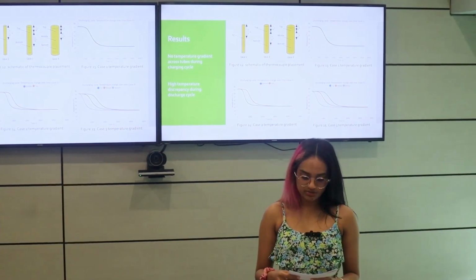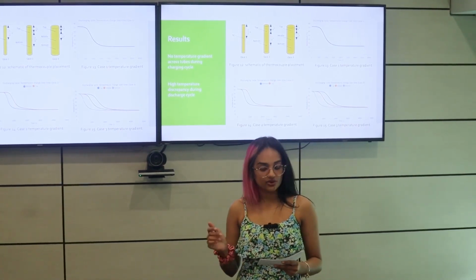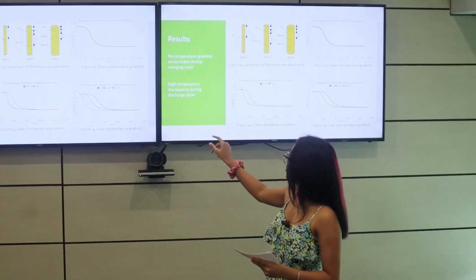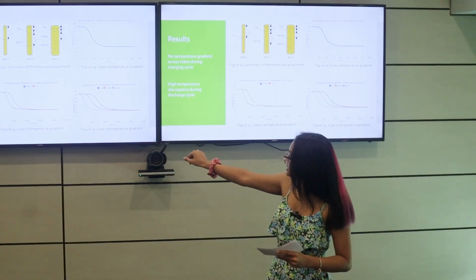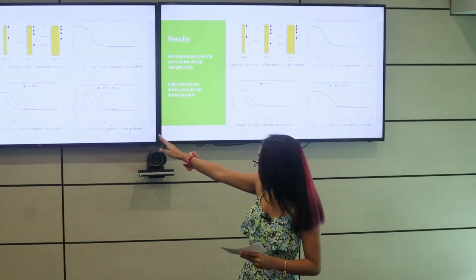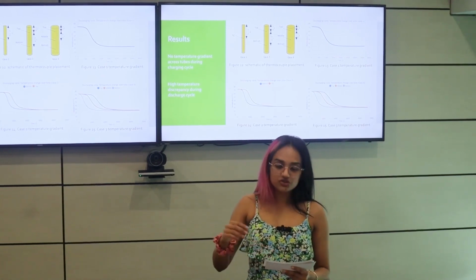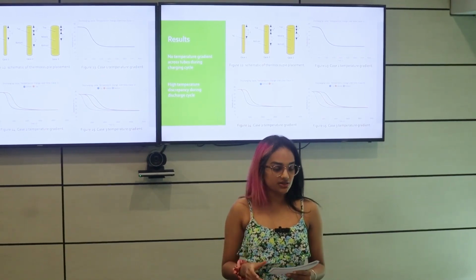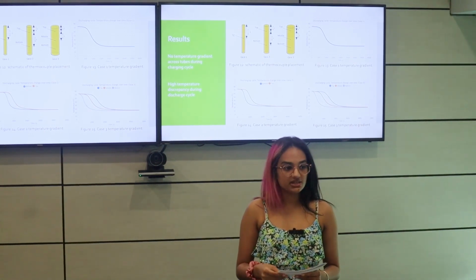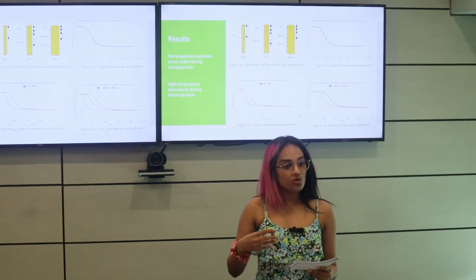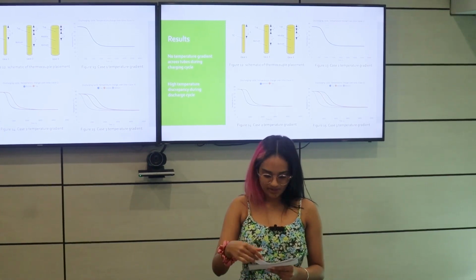One of the first observations to be made when I was analyzing the data is the significant temperature gradient which forms across the length of the copper tubes, as can be seen in cases 2 and 3. From these 2 cases, you can see that the bottom thermocouple and the top thermocouple were at extremely different temperatures at the same time. This gradient is as a result of the wax slowly solidifying, and as the wax solidifies, its density will increase, meaning that it will sink to the bottom of the tubes. The warmer wax will float to the top and be the last part to solidify.